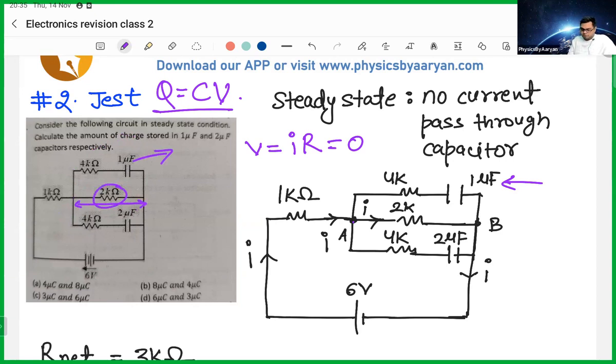इसके अराउंड वोल्टेज कितना है? So let's say इसके अराउंड वोल्टेज आ गया 10 वोल्ट. अगर इसके अराउंड 10 वोल्ट है तो इसके अराउंड भी 10 वोल्ट है. Voltage around this is also 10. But the voltage around this is 0 because current is not there. So all the voltage will go to the capacitor. So इसके around voltage will directly कितना आ गया?